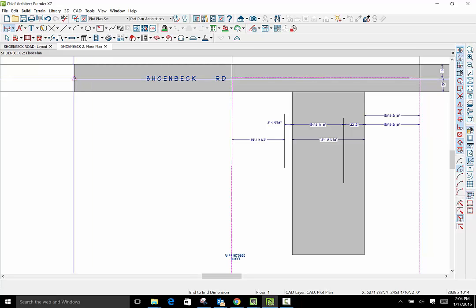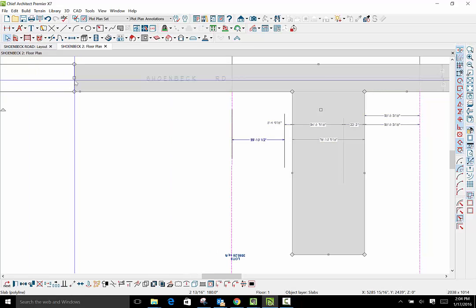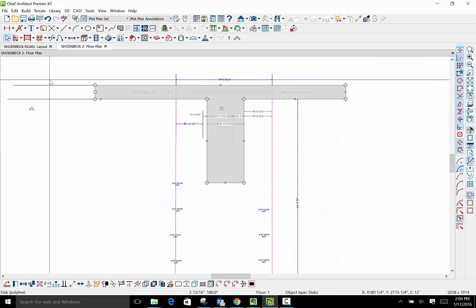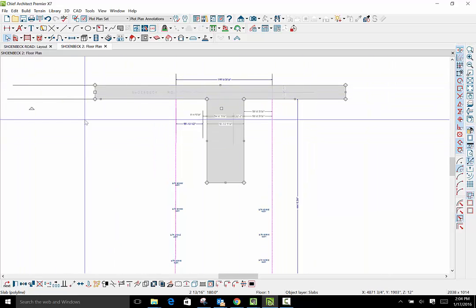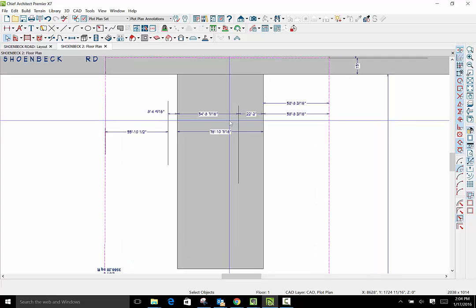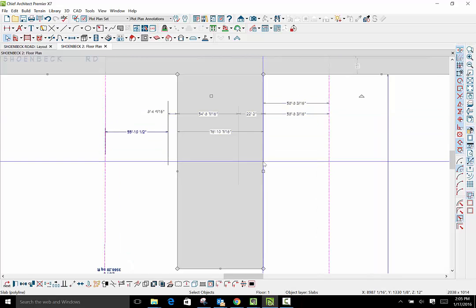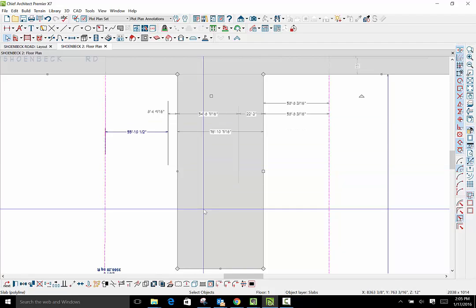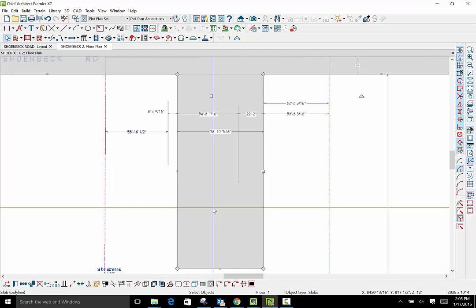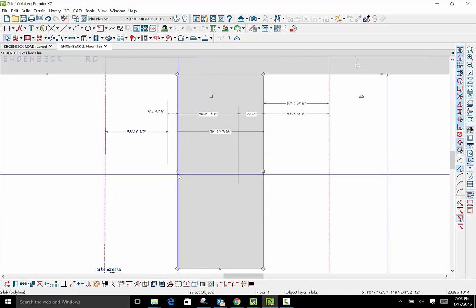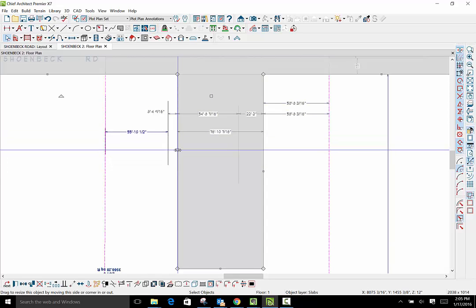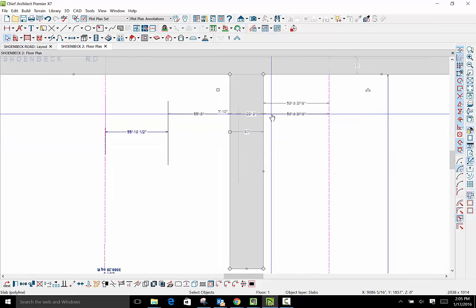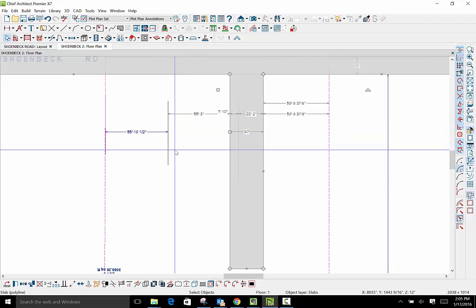All right, we got to put a street in there. And what I've done is I've taken a slab, started it, broke it in 2 points to try to create the street there, snapped it on top of the lines, 30-foot street. Let's put a 30-foot street down the center of this thing. So how do we do that? Let's see what happens if we take that line, click it, change it to 30 feet, and now we have 58 and a whole bunch of stuff going on there.